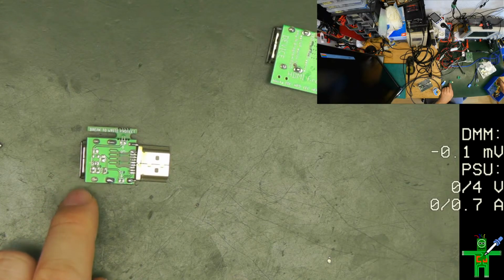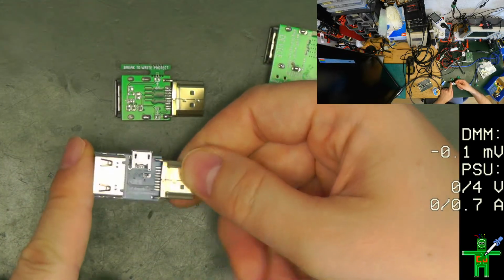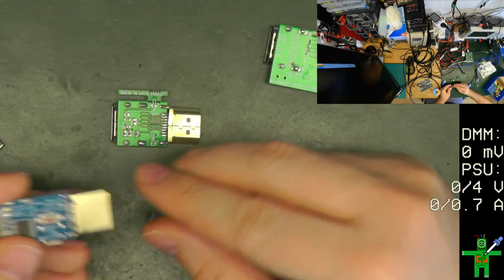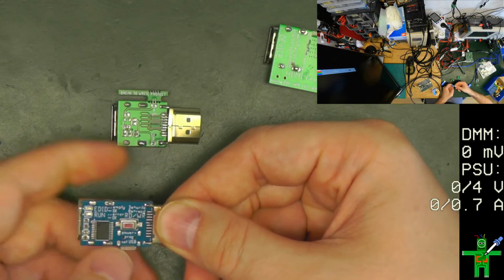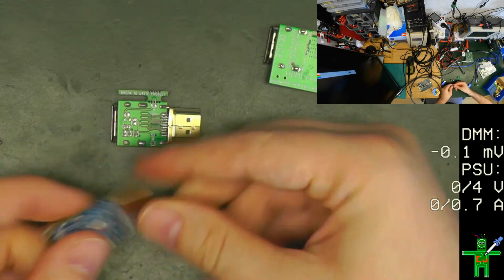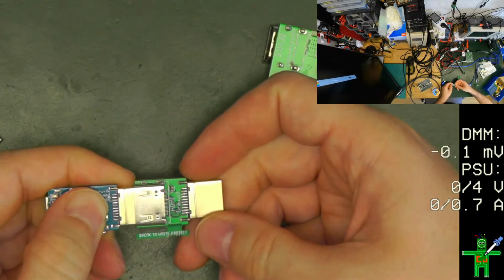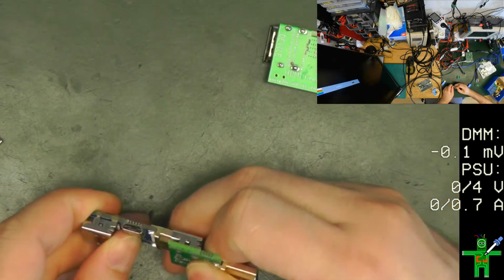Because of this shortcoming, I also created this HDMI firewall programmer, where you plug it into the monitor, you press the button so it reads the EDID information, then you plug it into the HDMI firewall and you press the button for longer, and then it programs the information into the EEPROM.